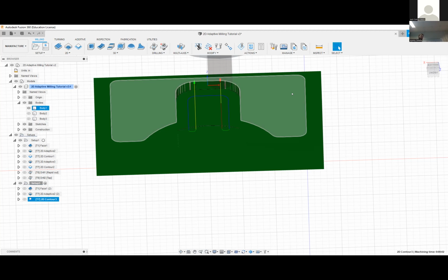And so if there's $1.2 million of parts sitting on a shelf that are possibly usable, the company is going to have you go through and check, does this part actually function even though it's outside of what's allowed? And so when you make a tolerance tight or you make a part more difficult than it has to be, that's the manufacturability side of things. So learning how manufacturing works is a great way to design good parts. And then even getting hands-on experience is a cool skill to have.